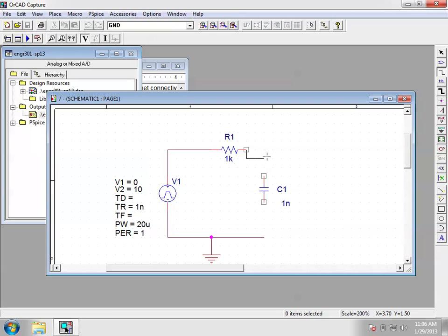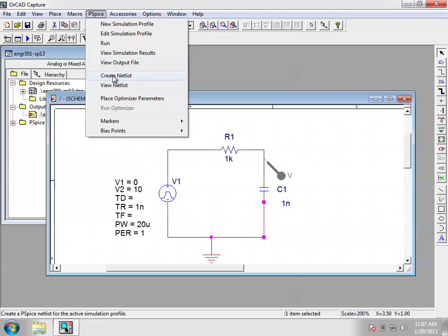And then run the simulation again. But before we run the simulation again, we need to do what? Got to add the probe. That's true. So I put the probe on here. That's good. What else do I need to do? The simulation is already specified. That's already defined. What's changed? The netlist, or rather, the circuit has changed. We need a new netlist to reflect this, right? So after we've done this, then you just need to create the netlist.